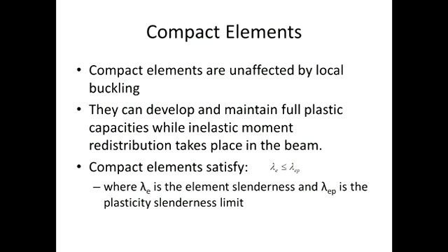So that's one of the characteristics. The section will be able to reach full plasticity and also allow moment redistribution to occur within the beam.